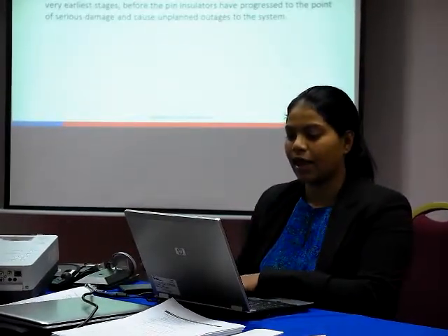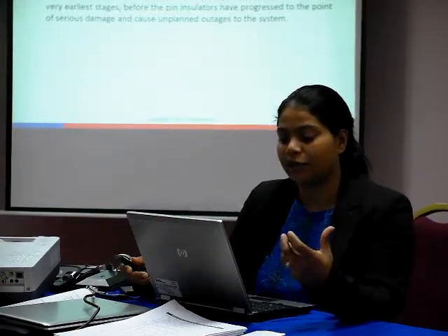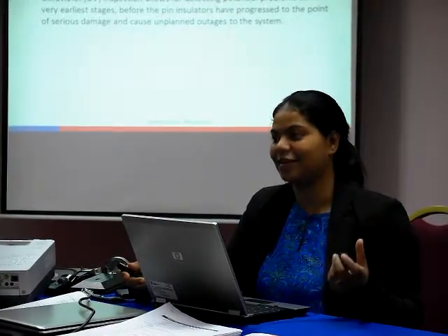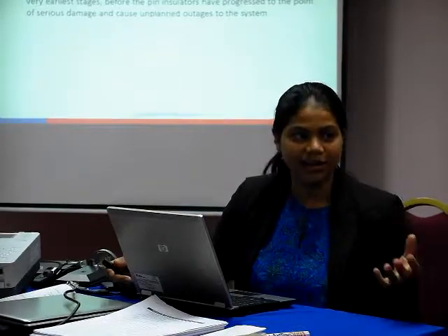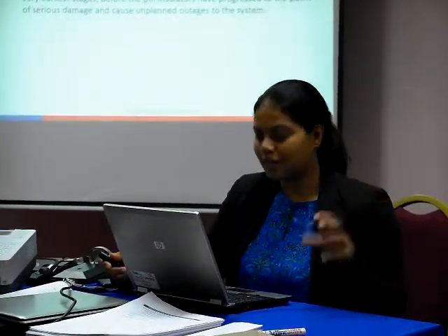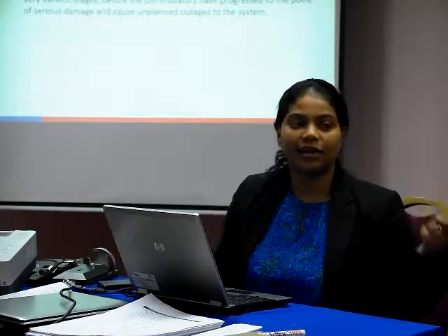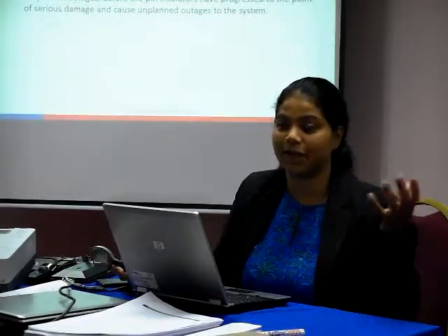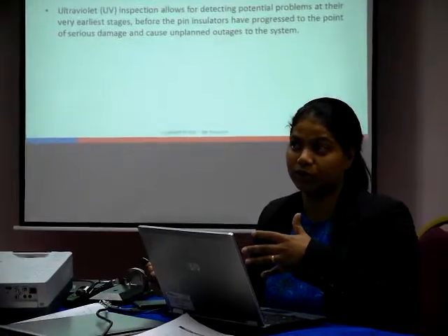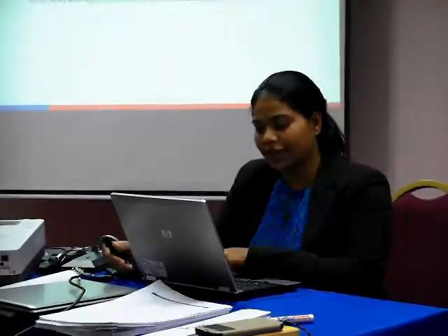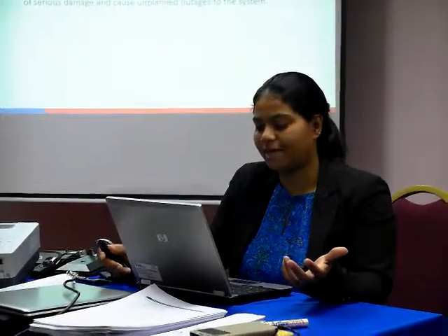Therefore, we in the NBR would like to perform a study to study the intensity of the surface discharge emitted from the degraded cap and pin insulator. So by doing this, we can also know if the ultraviolet imaging is a suitable method for us to get an idea of how our cap and pin insulator is going to be. Okay. So at this point, using this method, it will allow detecting problems at initial stage and before outages to the system. Okay.